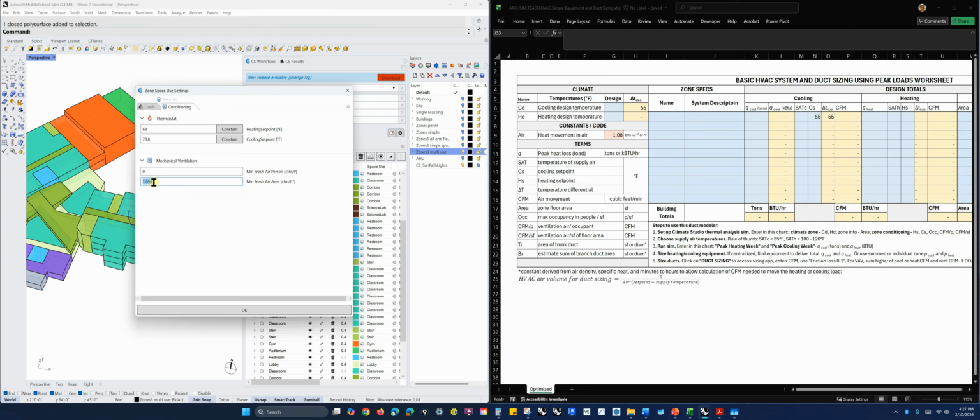There's probably a fume hood, so this is a general setting to take into consideration that amount of air transfer. And of course, we talked in the last video about how, in a peak heating load situation, that means we're going to have more air moving out of the building that we've conditioned. Hopefully we'll have some kind of energy recovery ventilation, but we're going to lose heat there, so that's going to raise our peak heating load.